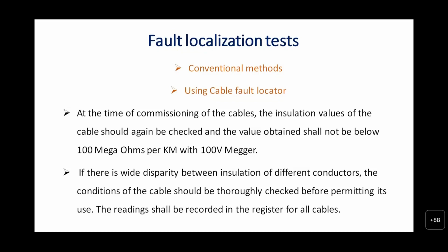If there is a wide disparity between insulation of different conductors, the condition of the cable should be thoroughly checked before permitting it to be used. The reading shall be recorded in the register for all the cables. If the disparity is too high, the cable should be rejected and a different cable should be laid.